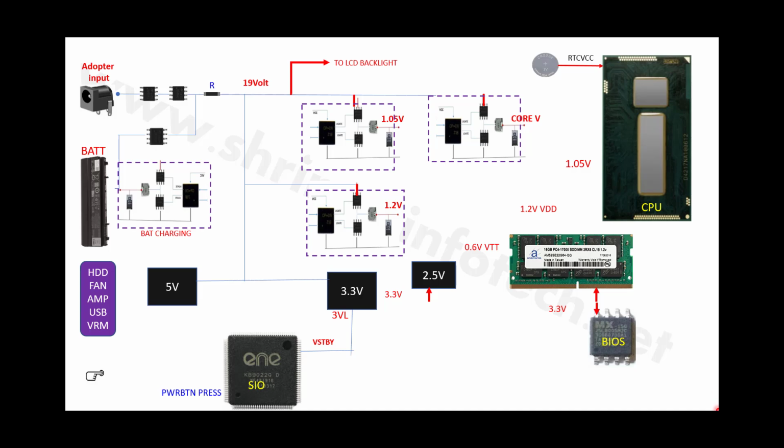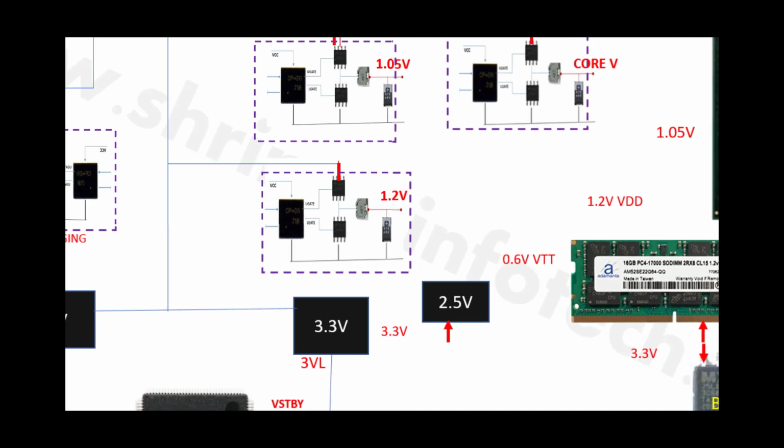So in this video we are going to know about how to diagnose or how to detect the short circuit in the motherboard. Here I have some concept on the screen. This is basically the power inputs, the power jack, adapter inputs, and this power flows through these two MOSFETs, and here is the current sensing resistor.